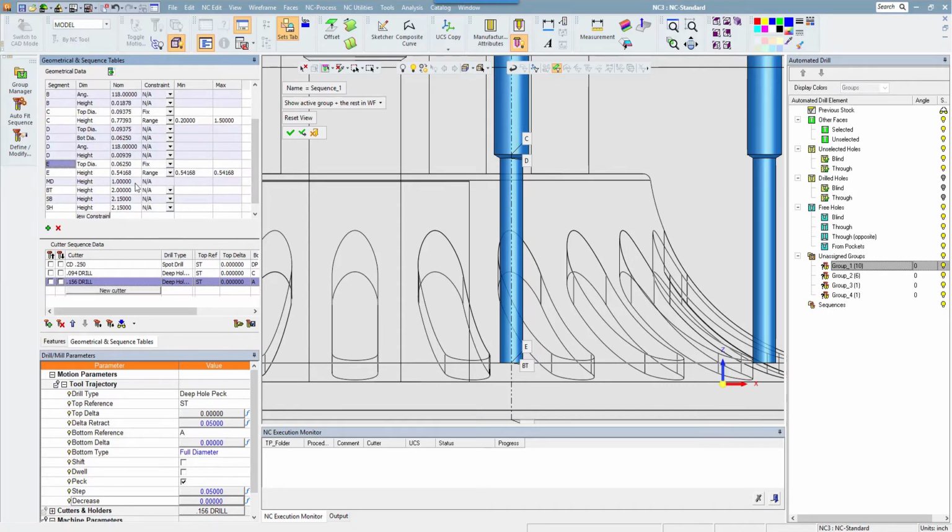So now we're on E, this lower diameter. We're not going to drill this because this diameter, 062, over that length, it would wander. It'd be no good. You'd probably wire this or drill it from the other side. But we do want this sequence to fit on exactly this type of hole, right? An 062 pin drilled from the back. So we need to reference this diameter to have it come out right. So we're going to leave the diameter fixed.